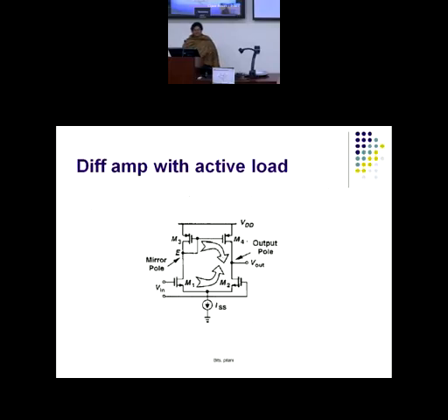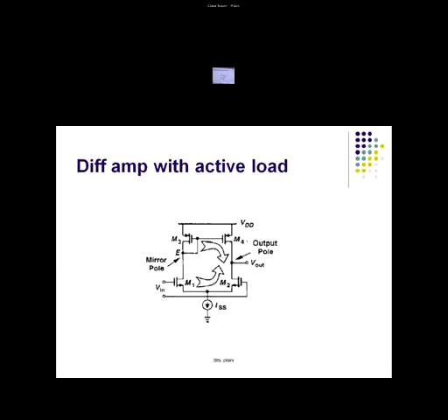So actually initially, remember, for fully differential, you were having only two nodes, in and out. The moment you go to single-ended output configuration, you get three nodes. Immediately that gives you a feeling that this will have one extra pole, because every node has a time constant. So this will add to the number of poles. And I told you, the lesser the poles, happier we would be, because poles means degradation in the gain. I do not want too many poles, too many zeros. I would be very happy if no pole comes up.